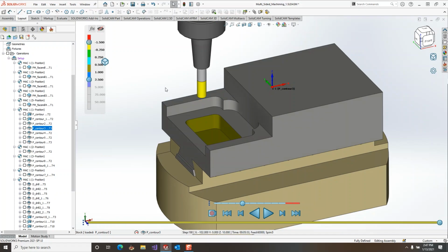You can also measure between multiple points. For instance, we can take a point and another point, and we can get the measurement between those. So you get the distance, the 3D distance, the distance in X, Y, and Z. You can also measure between two lines, for example, and you will get a distance measurement. You can also measure between a face and a vertice, and you will get the shortest distance.